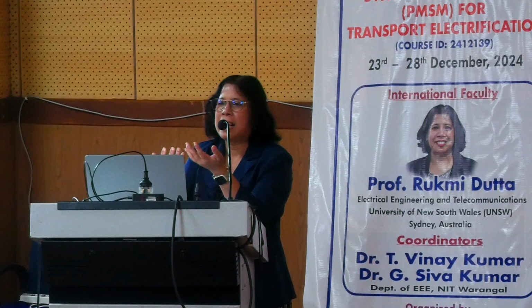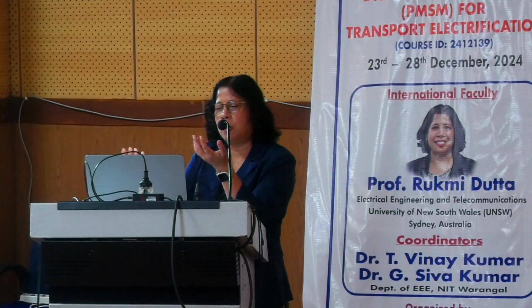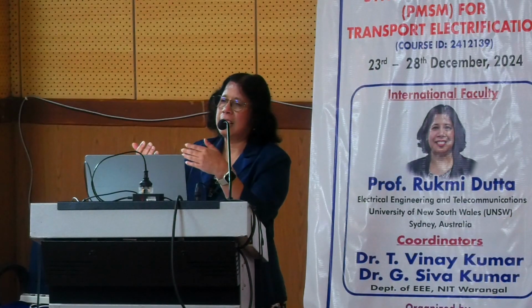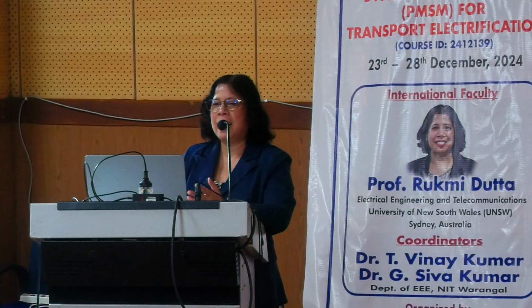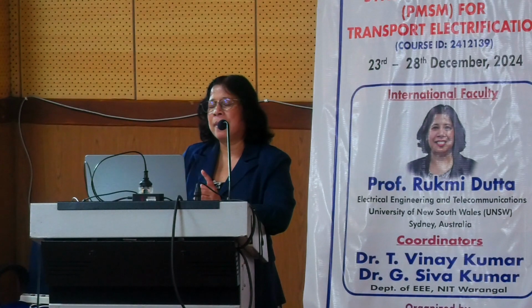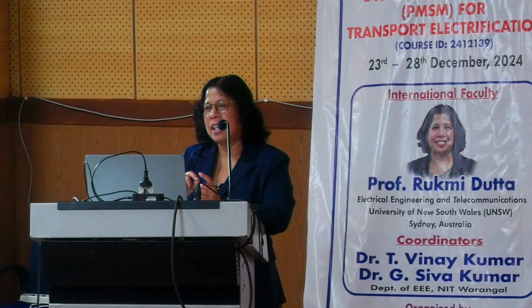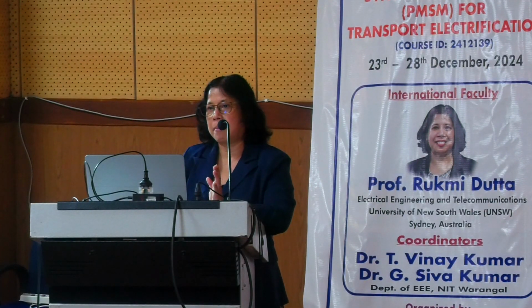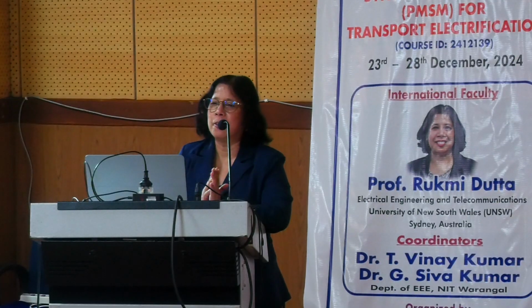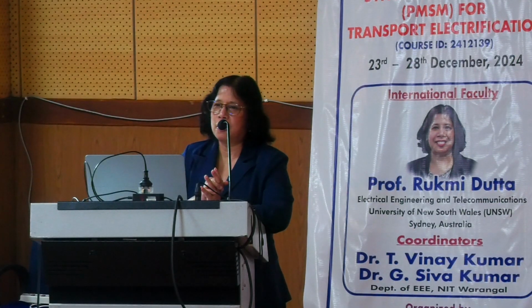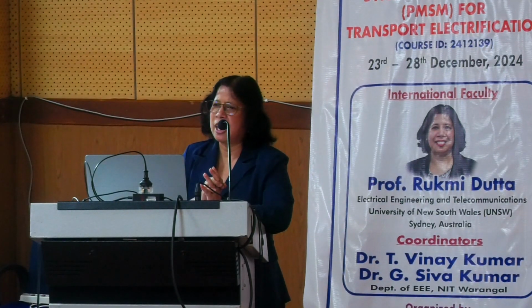Next, let's say you go to 1 RPM. So at 1 RPM, whatever the equivalent frequency, you increase the voltage equivalently, right? This happens through your FOC itself directly. So you don't need the damper winding, neither do you need V by F or I by F startup. It will start automatically if your FOC is working properly. It's just how good your controller tuning is. If you tune your controller nicely and perfectly, there is no problem with startup with a sensor.